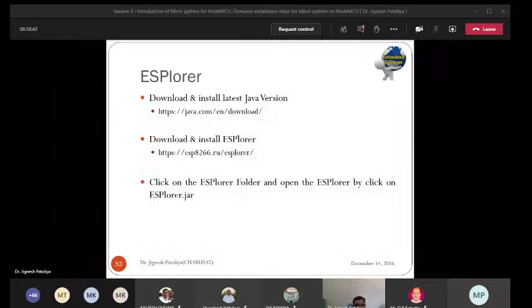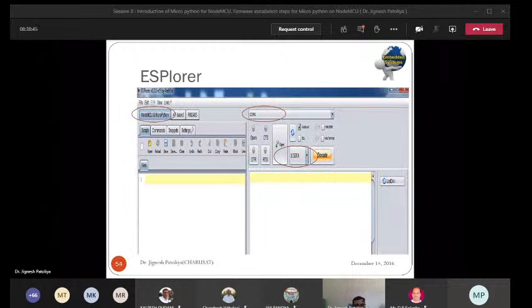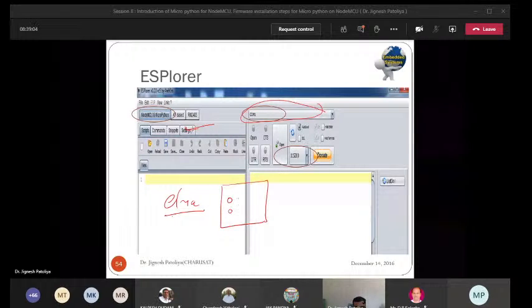Similar way, in the second option, ESP loader, this is a screen of ESP loader. First of all, here we have to choose a particular comport, and one interesting thing, by default it is Lua. So once you start with programming, then click on settings. Once you click on this setting, one window will pop up and two radio buttons are there. Initially it is on Node MCU.